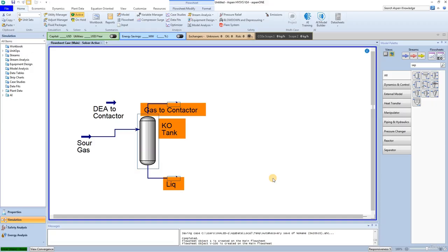The major operations in a gas sweetening flow sheet are the column models: the acid gas amine contactor, modeled as an absorber, and the amine regenerator, modeled as a distillation column. These column models will be set up a bit differently than typical HYSYS columns due to the strongly non-ideal nature of the amine acid gas separations.